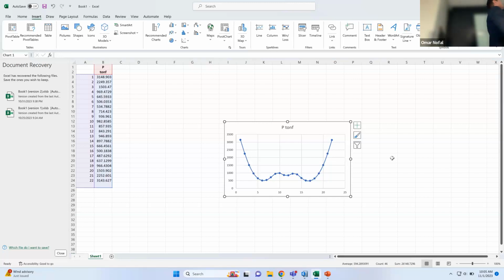And this is how the shear lag looks like. Can you see? You'll tell me, okay, so why does it look like this? It went down and then it goes up again and then makes like this. Why didn't it go all the way down? Does any of you have any outriggers? Because of the outriggers. Because you have outriggers in your model. So when you come at the middle of the building where you have a core and this core is connected with the outrigger, this is where the core is. It's connected with the outriggers. So it makes a shift a little bit because it makes the columns at this area, because if you remember, we have our building like this, and there's a core here.